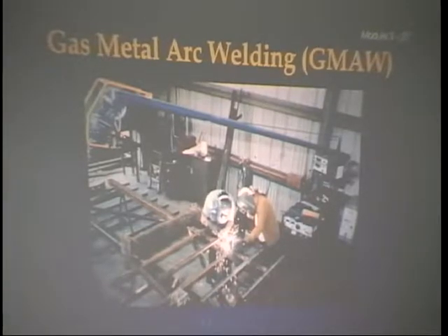Now, looking at page 748, I'm beginning in the second paragraph in the first column, which reads, the complete name for GMAW is gas metal arc welding. That's a bullet. You should understand that. Slang and trade names are often applied, such as MIG for metal inert gas, and MAG, metal active gas. That would be your reactive gases, like some of them will have a little oxygen in them, for example, or straight CO2, which is a reactive gas, as opposed to the inert gases such as argon and helium. So understand that name, understand MAG, understand MIG.